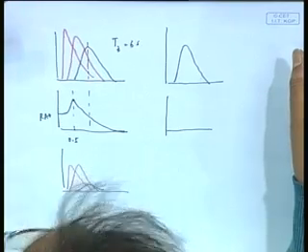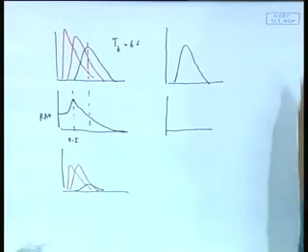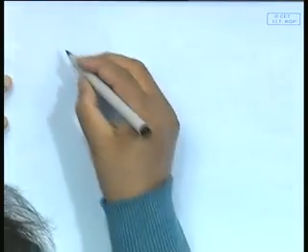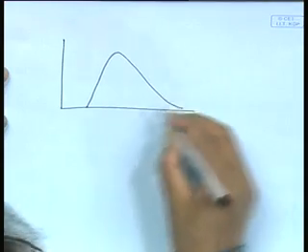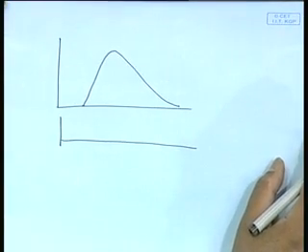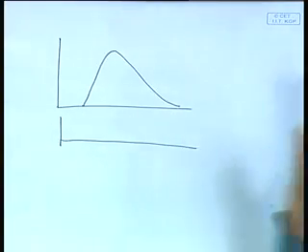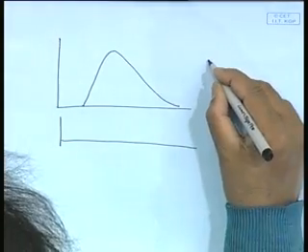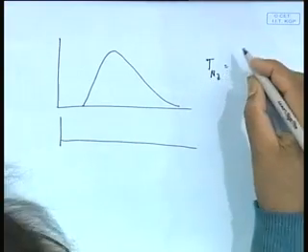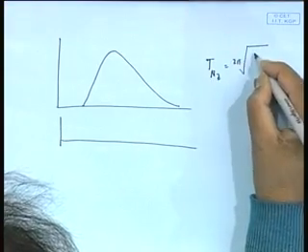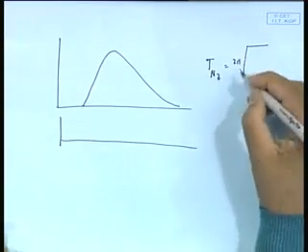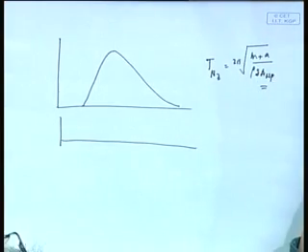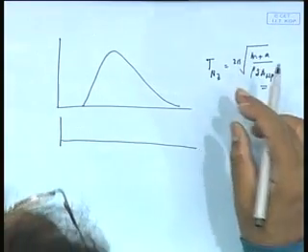Now, you see, if you take a barge, very long barge, we discussed this at one time, or rather let me put it this way, pontoon barge and spectrum. This is also interesting about the response part. See, there is a typical spectrum and I will take 3 different cases. Now, if you take a particular pontoon type of thing, big thing, what would happen? It has got a small natural period, high natural frequency, because you see T natural in heave is, what is the formula? 2 pi root over of, no, omega was, m plus a divided by rho g AWP, right. Now, if AWP was very high like a pontoon, my Tz is very low, it can be 4-5 seconds.